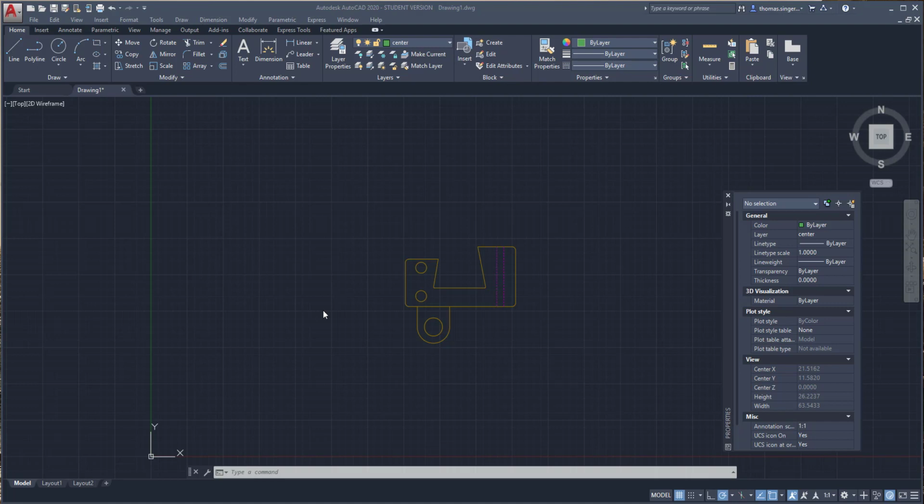Today we're going to be focusing on putting dimensions on a drawing. This is a specific drawing that I've used a few times to do dimensioning practices because it's got a variety of different dimensions that need to get placed. But before we can actually start on dimensions, we need to put center lines and center marks where the circles and arcs happen to be placed.